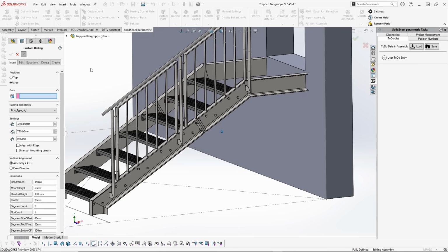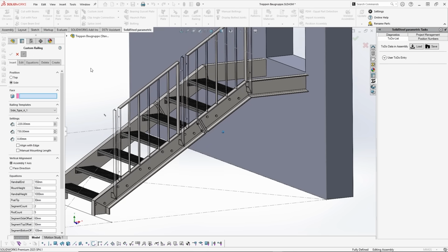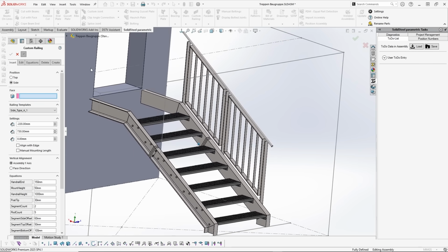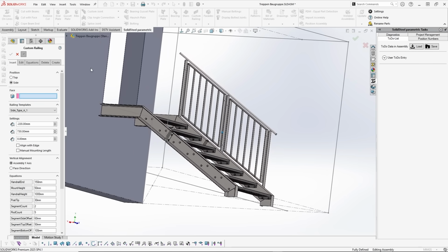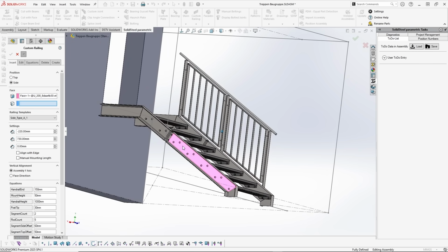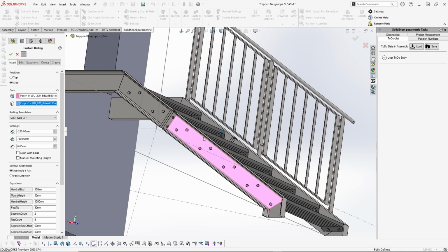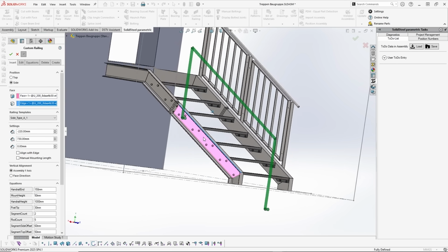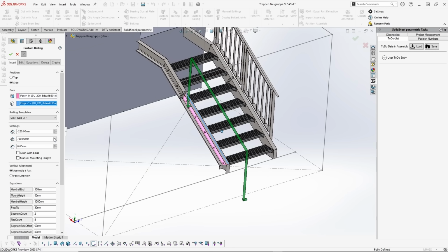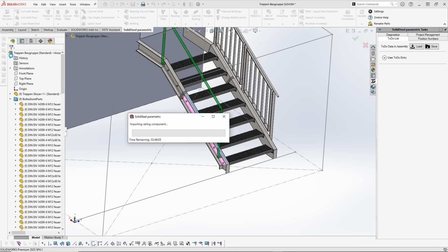The parameters we just mentioned can be seen in the lower left of the dialog. For example, mounting distance, height, number of segments, number of bars per segment, and so on. It would be tempting to continue building the railing at the top right away. But since everything is set correctly, it's smarter to first place the identical railing on the opposite side. Because it is mirrored, we need to swap the start and end offsets. Everything else can stay the same and we can confirm to insert the railing.